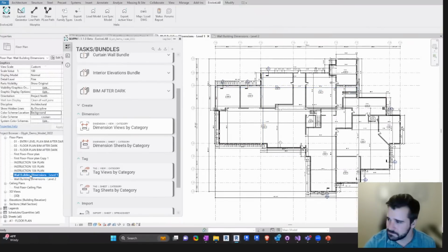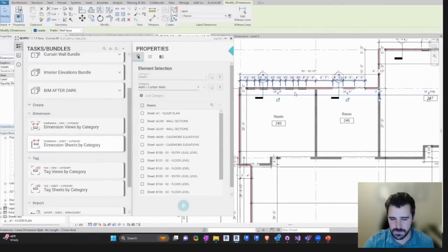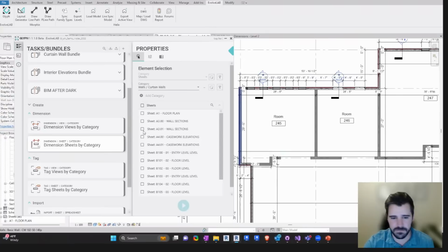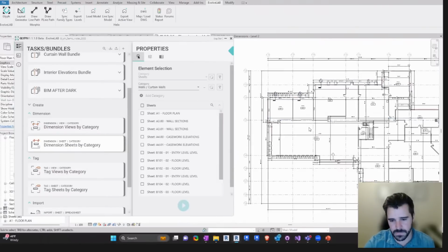So when you were setting those settings, I saw you tweaked, I think it was a 2.5 foot dimension. Is that the offset from the wall that you were showing? So that's mostly for the exterior wall. Then the next one was 2.5 feet from each other. So if you wanted it to be a little further away from the wall, those are the settings you were tweaking there, right? Yep, for sure. And the interior is going to try and find just the most efficient location to get across it, and that'll be where it lands.